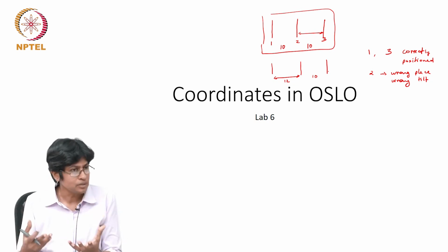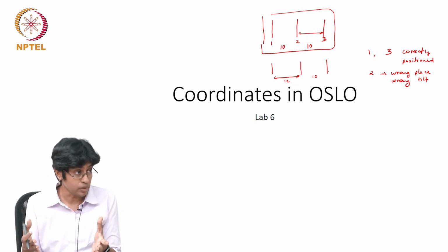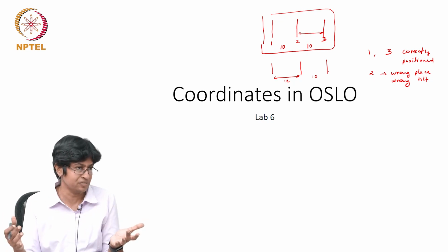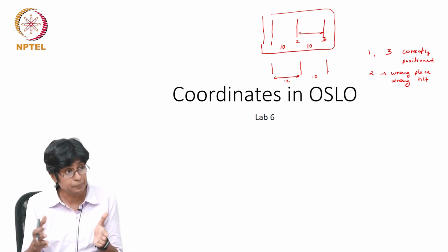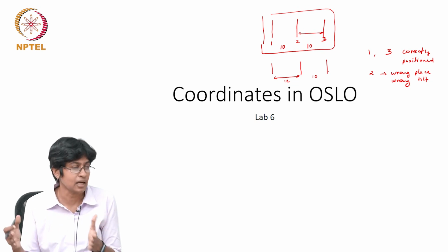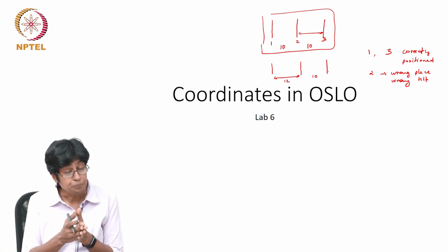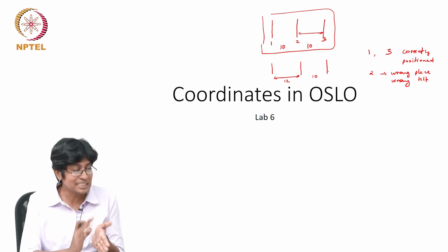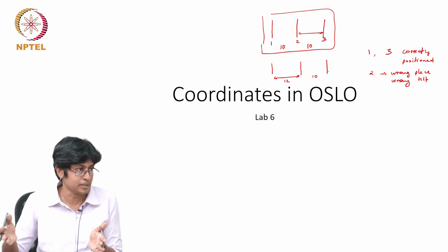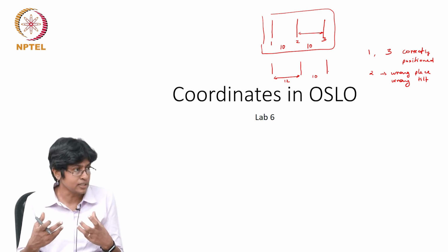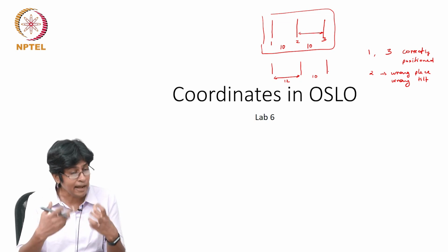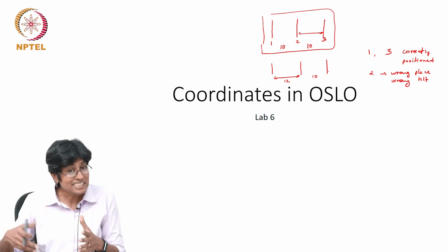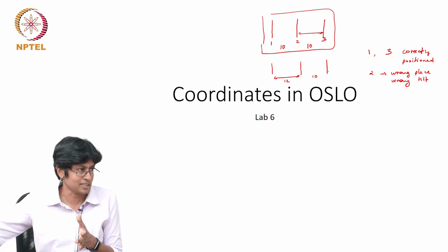So, in order to study such cases, and they're very important, once you have a perfect optical design, or what looks like a perfect optical design, what people will do is run something called a Monte Carlo simulation. So, they'll put in all the maximum values of error for the tilts and positions of each element, and the Monte Carlo simulation will assign a random value that lies within the range for each element and see if the overall result is acceptable.